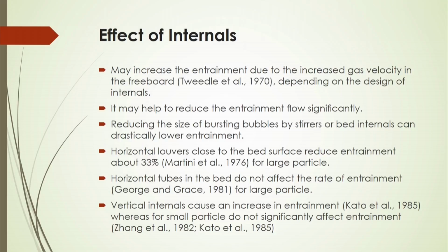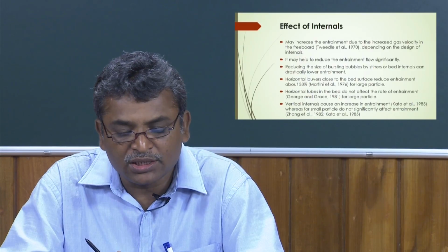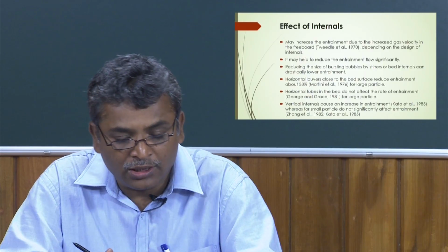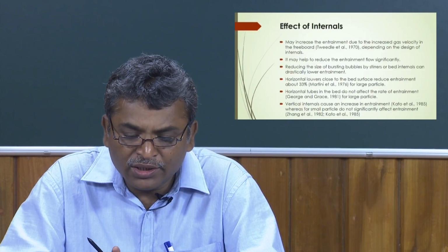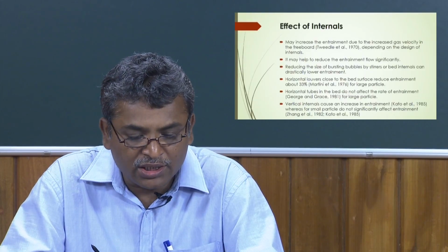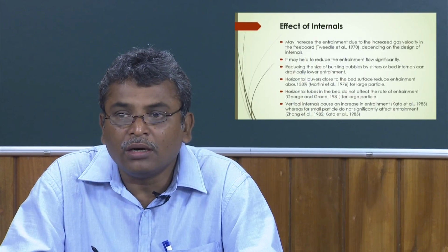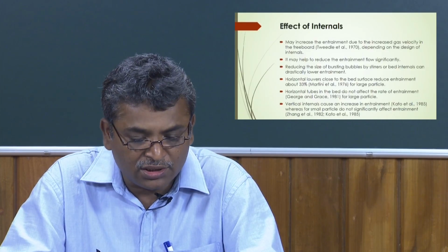It may increase the entrainment due to the increased gas velocity. Suppose you add some tubes or baffles inside the bed, then the actual velocity of the gas will change, and because of that the entrainment will change. So the entrainment will increase with the gas velocity, because of that increase of gas velocity by just internals, depending on the design of those internals, of course.